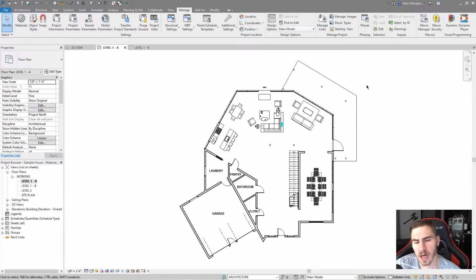And so I would actually make a box or a cube or something and then paint a particular face of that object if I have a material that's only applied to railings or any sort of wall sweep or gutters, because that material by default will not fall within a finish schedule.